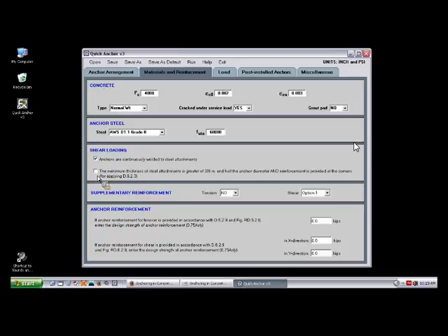So if you meet this second condition, then you could achieve a slightly higher shear breakout strength of the anchors. Although it's not necessarily higher, there is an equation that gives you a little higher value in shear breakout, and the first option also works with that. If you do qualify for both of these, then you do get that little advantage you might get.